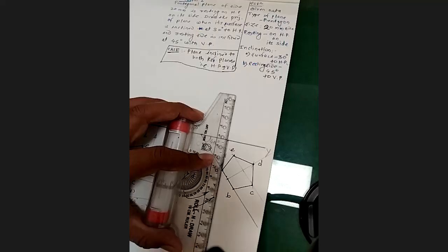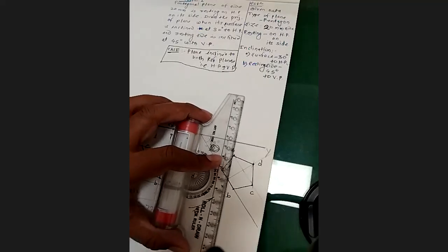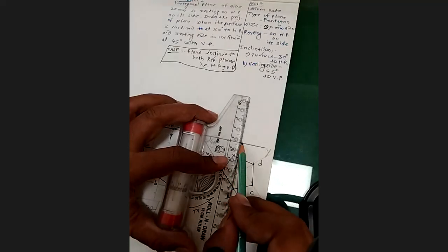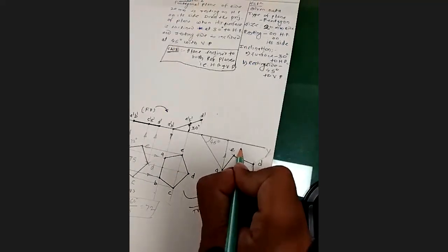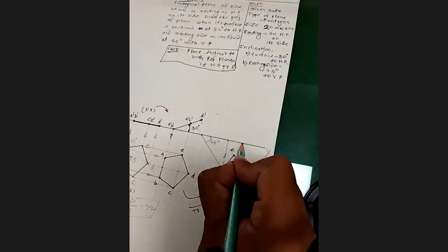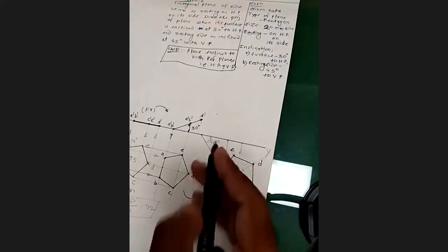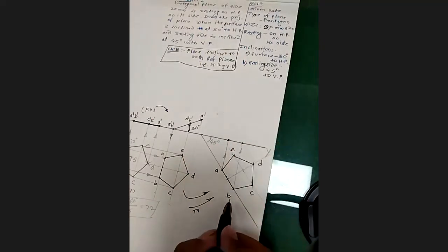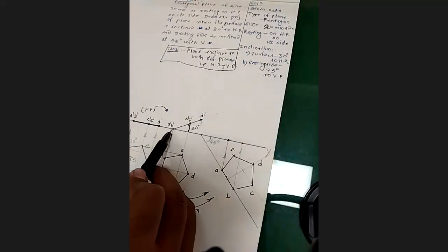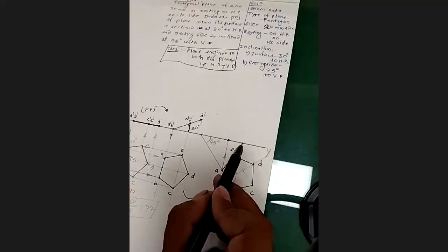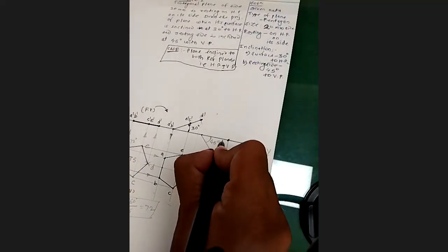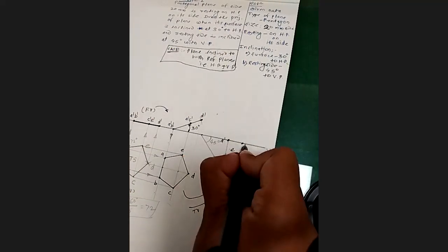Similarly, on the same XY line, you are going to get the point B. So I will take the projection from B, and I will get this point. Immediately I will mark this point. See, this B vertically and the previous stage front view B horizontally will intersect at this point. So I will immediately name this point A dash, B dash to avoid any further confusion.